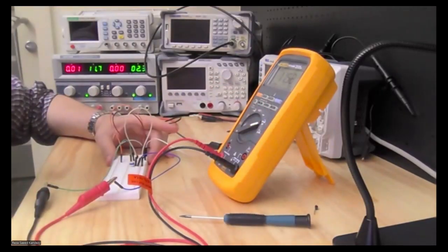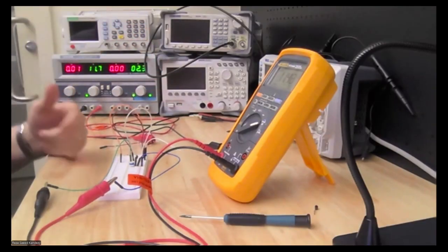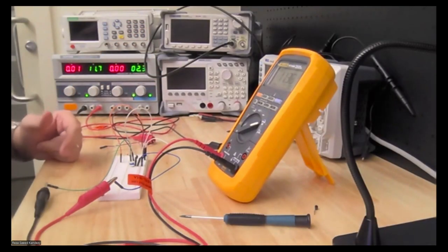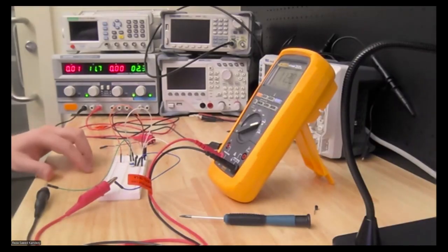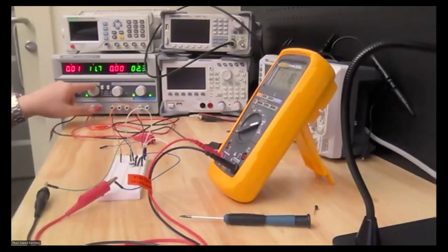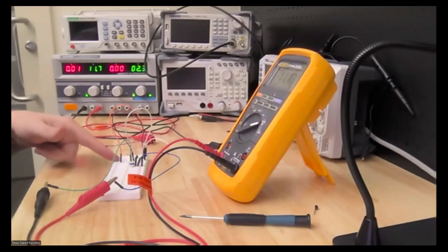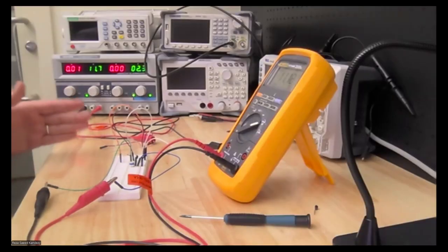Now, if you wanted to have the IV characteristics of your BJT in our system, you can change the voltage in a DC source and you can sweep. That way you can change the current injected into the base. You need several points, at least 10 points.